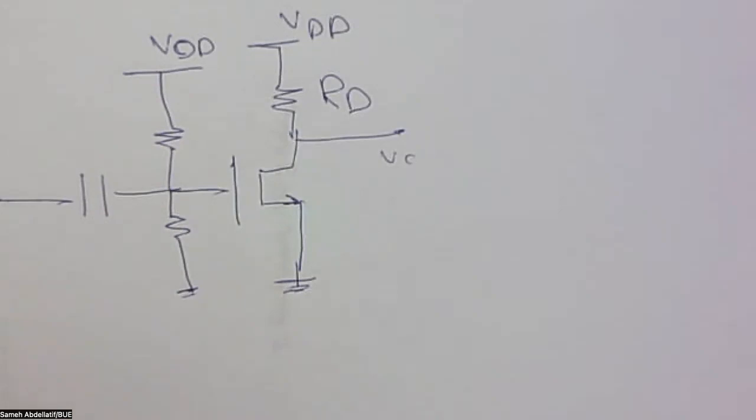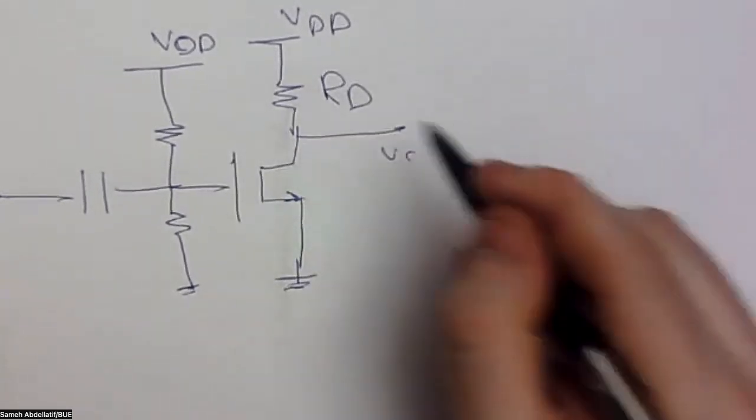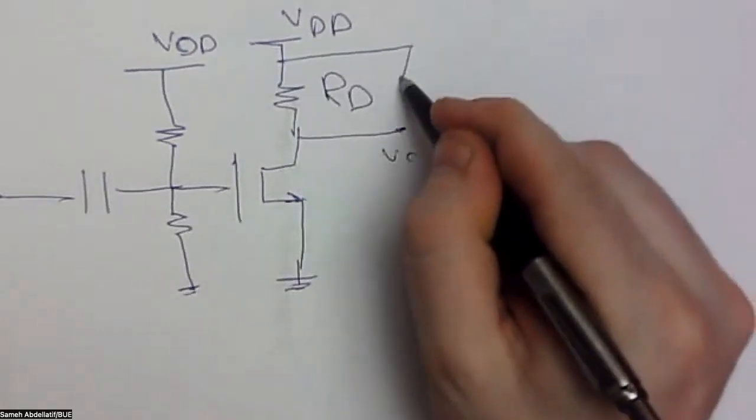And I'm sure that all of you have already solved a lot of problems in electronics 1, 2, maybe in 3, but mostly in 1 and 2, where we have this common source configuration for a transistor. But now the question is, this is a direct amplifier, but what we are searching for is both: an amplifier and a filter. So what if we turn this load, this RD, not only to be in this format, but also to be like this?